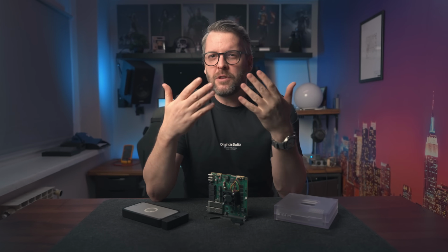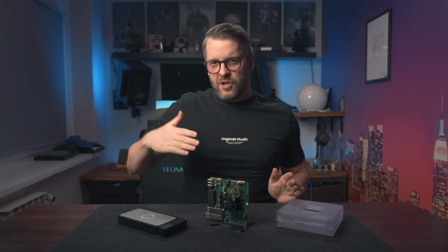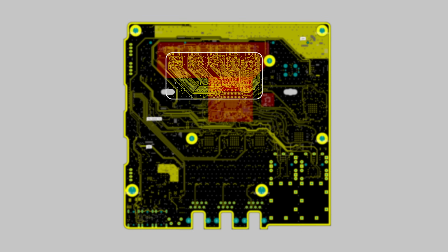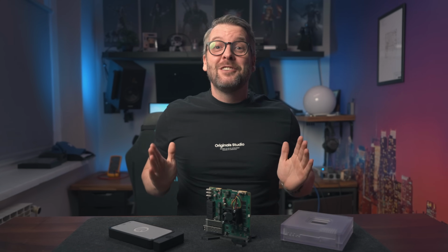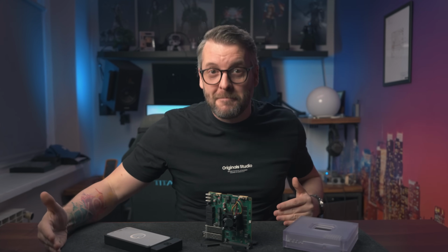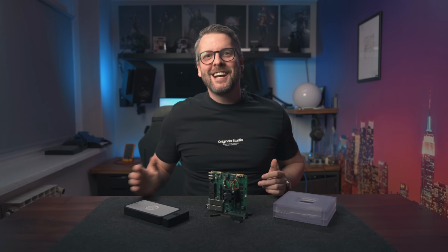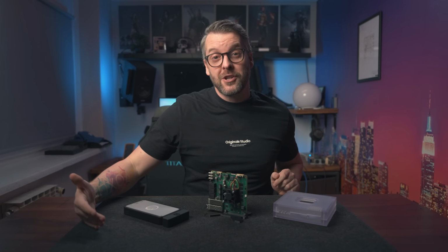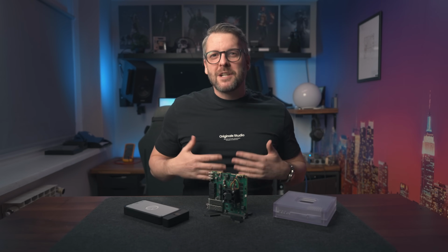Basically, when we were routing the traces on the PCB, we mistakenly swapped a couple of traces, which, as I said, is perfectly fine and within standards, and honestly an easy mistake to make given the complexity of routing memories. But when you do that, you still need to tell the controller how bit swizzling has been done so that it can configure itself properly. But because we thought we routed traces without any bit swizzling, we misconfigured the controller, which in turn resulted in the automatic calibration error. Obviously, those couple of bits being swapped wasn't done on purpose.